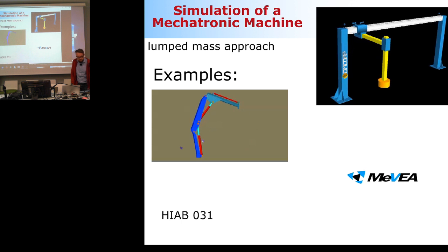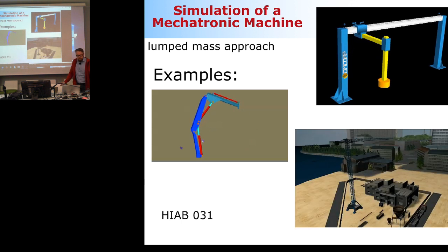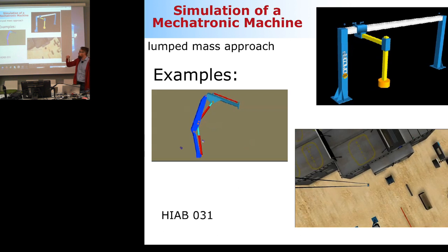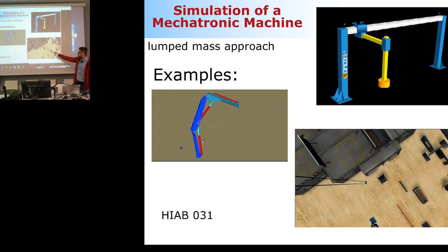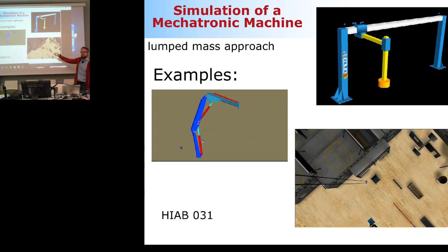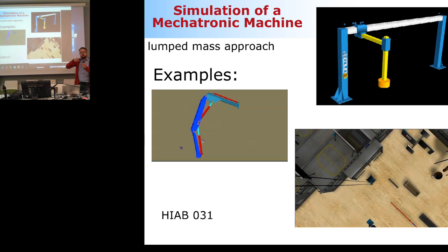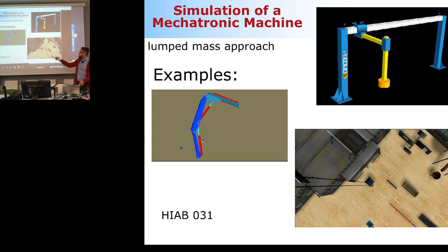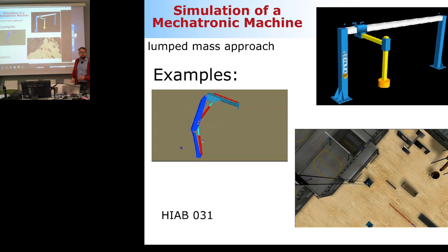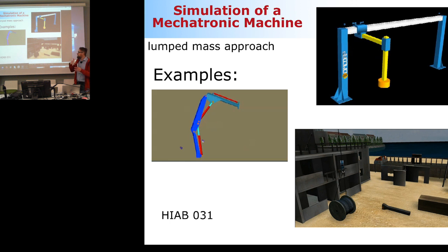This is an animation that shows how it is used in cable elements. The figures will be a little bigger than this, but soon the viewpoint will be different, and then you can see the cable or the wire rope. This wire rope is actually modeled by using these lump mass approaches. So it's rigid particles that are connected together via strings, and it looks pretty much like how it behaves in reality. So this is still a valid technique in certain special applications like wire ropes.